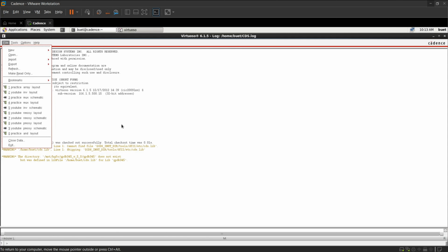So today we will be looking into the next video of analog layout design, that is how to do analog layout design of a 2 input NAND gate. So launch your Virtuoso in GPDK 90nm and go to new cell view.